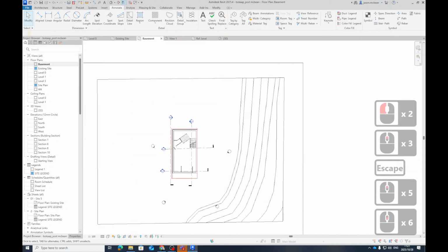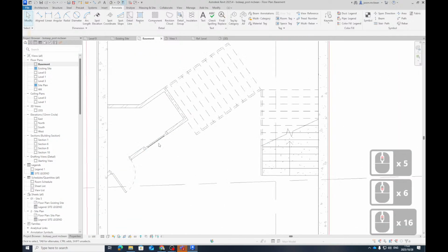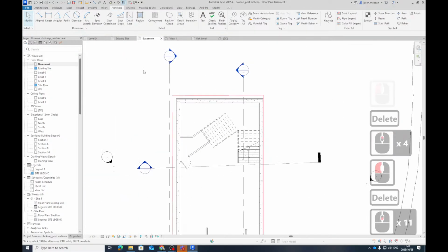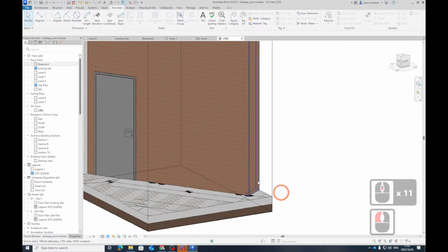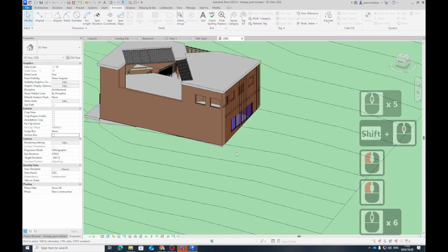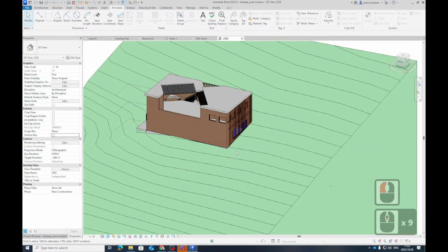Okay, cool. And then I have one last question. I need to fill a gap that I have created. Let me go to my basement view. I have cut these holes, and I now need to fill them with soil. You can use another slab that's slightly lower and use another material, and then you just select the outline and you fill it. Do I select that sweep I have created as the fill line? Oh yeah, because now you've got that shape.